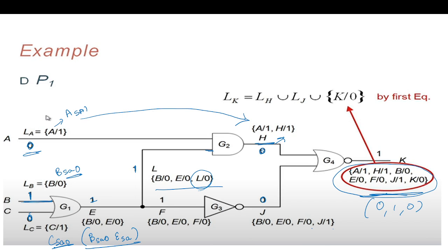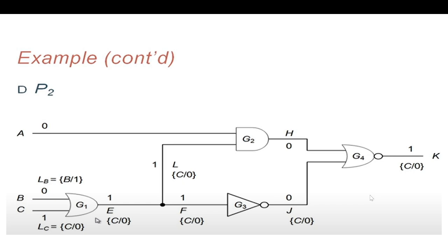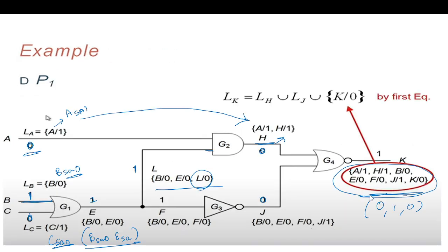So this is very efficient to simulate, as we can get this many faults in just one pass. But it is not easy to handle if we have an unknown here, then we can't reason which faults are going to be detected. And this can be useful only for a zero delay model. There is also a memory management problem, because we have to handle these lists.